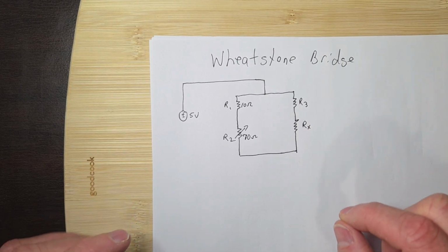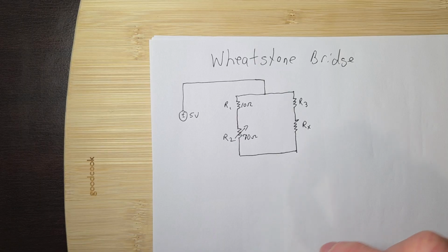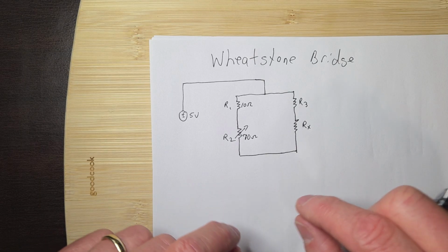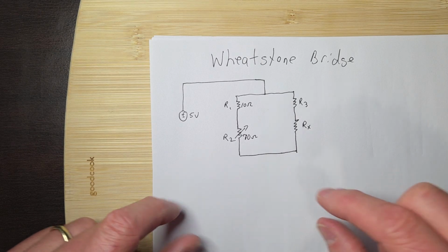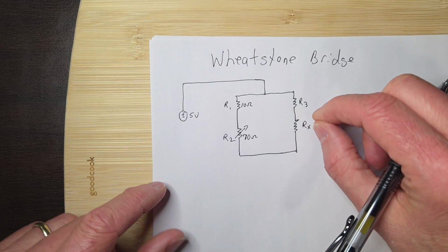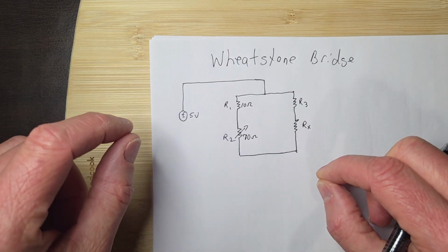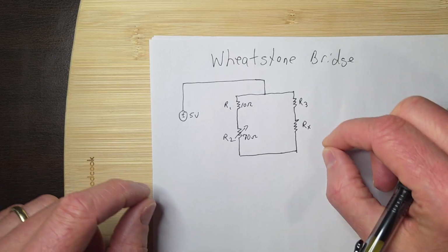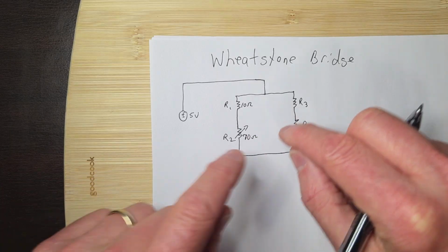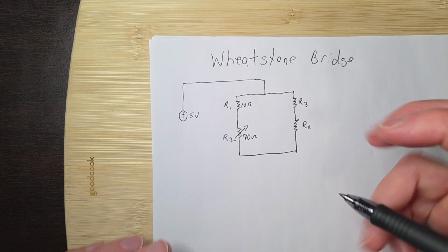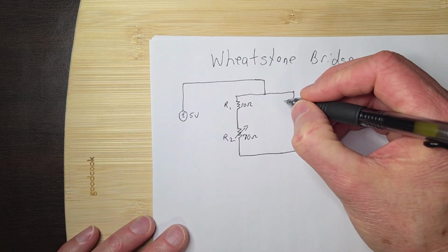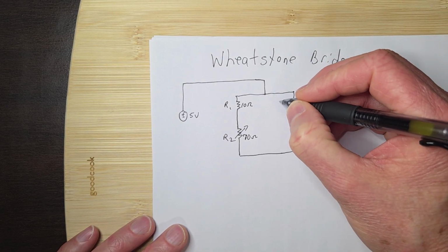As the rocket went up, they wanted to measure the G-forces by measuring the resistance. So we had a Wheatstone Bridge in there, and when the strain gauge would bend, when it would lift off, or when it's coming down, it'd bend the opposite way, then you could measure the differences in voltage and turn that into something useful. You could calibrate it and turn it into something useful.